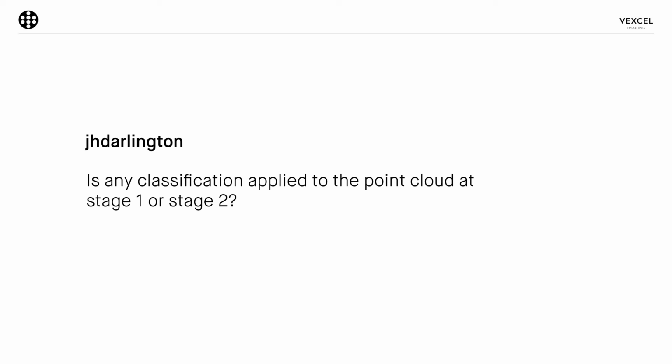However, the point clouds that we can export have RGB values for the points, and optionally we can also integrate the near infrared. So that information is available. That could be used then in third-party software to do analysis or classification as needed. Especially the near infrared is very helpful to do some classification on the data.